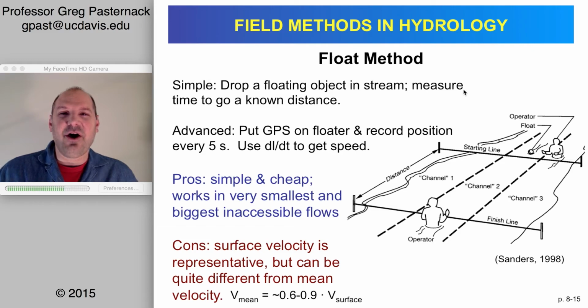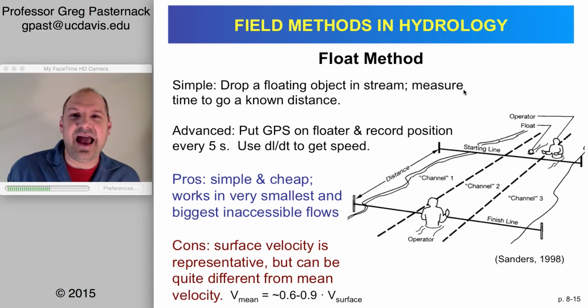There is now a far more advanced method to do this. It's something that I've been doing a lot myself, actually, and other people have been doing. It certainly isn't something that I came up with. But the idea is that you just take a GPS, and remember, a GPS measures your position. So if you can put a GPS in a waterproof bag or on some kind of floating platform or boat, and if that is moving with the current, then simply let it take your measurement every 5 seconds or so, and it will be recording its position at that time interval.